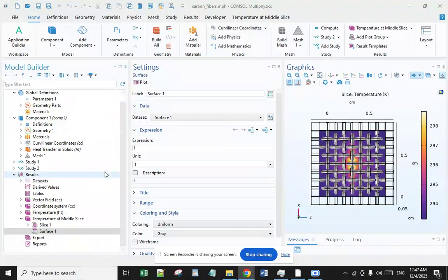A biaxial non-crimp carbon fiber fabric, the NCF 300 biaxial, has an areal density of 300 grams and a measured uncompressed thickness of 0.70 millimeter. The NCF consisted of two identical plies at 90 degrees orientation held together with a polyester yarn in a straight plain stitch pattern with a pitch of 5 millimeter.